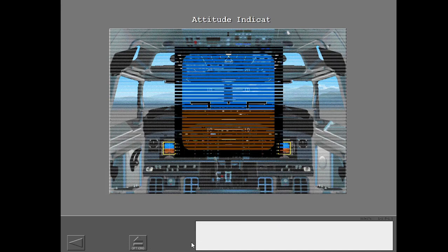The scale turns amber and the pointer flashes to show large localizer deviation. The glide slope pointer shows glide slope position in relation to the airplane's position. The scale turns amber and the pointer flashes to show a glide slope deviation greater than 1 dot.